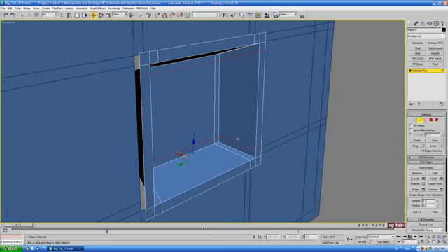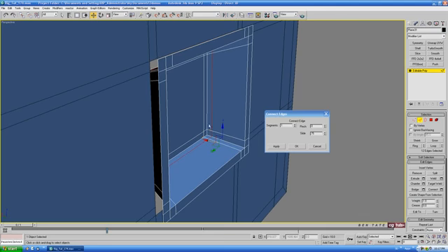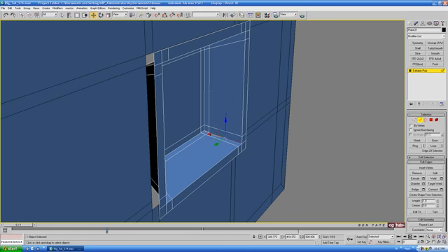Okay, we also need a couple of support edges around these edges here, so let's bring this one and connect it up. And let's maybe just do 1 here, no pinch, and let's go slide that towards the back. The reason why I'm only doing 1 at a time is I want the back to be a little bit more soft and the front to be a little bit more hard. Alright, so we'll put 1 there, about 75 or so on the slide, and then we'll ring the edge again and slide another segment towards the front. And we'll do maybe about negative 85 on that one.